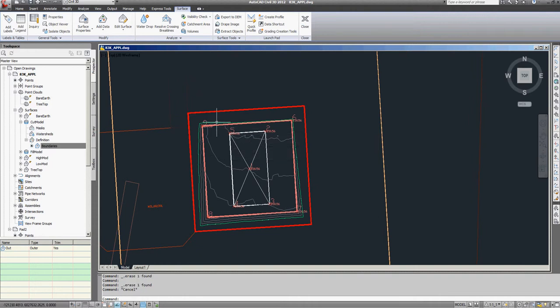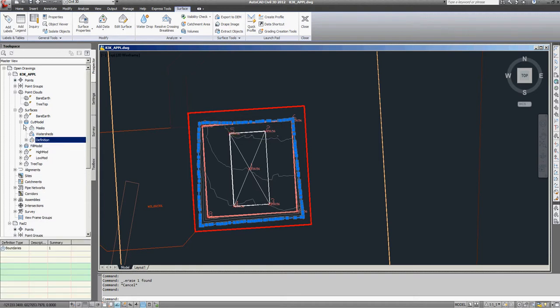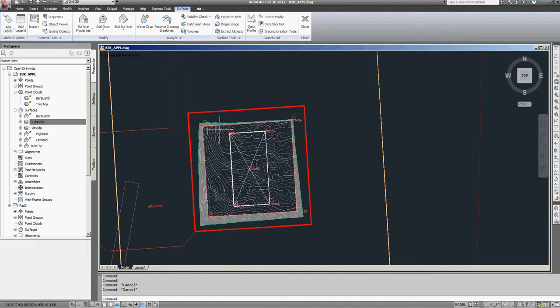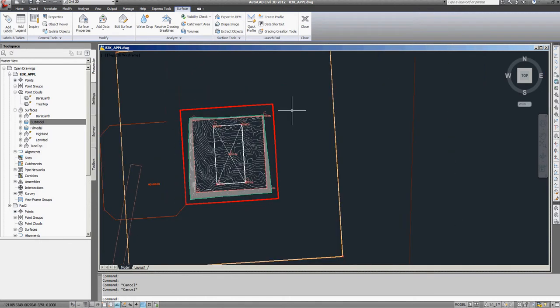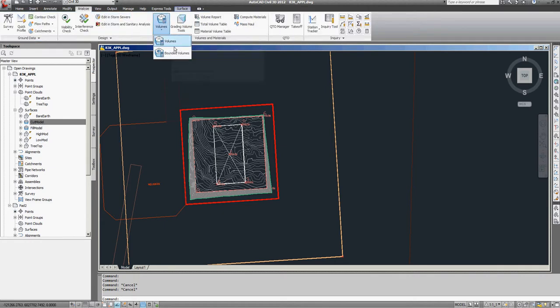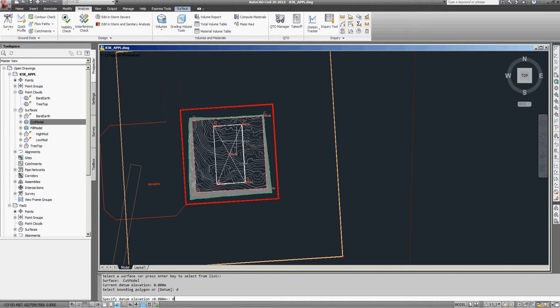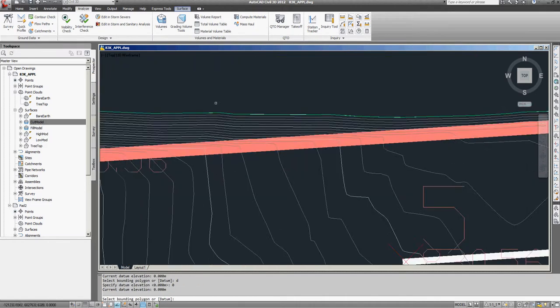And we could calculate a total volume quite simply, if I wanted to see even what the contouring was on that cut. We'll just change it here. And we'll see now that the entire lease gets cut and the entire volume is now going to be the cut model, 0, and select the bounding polygon. We're going to have 23,000 cubic meters.